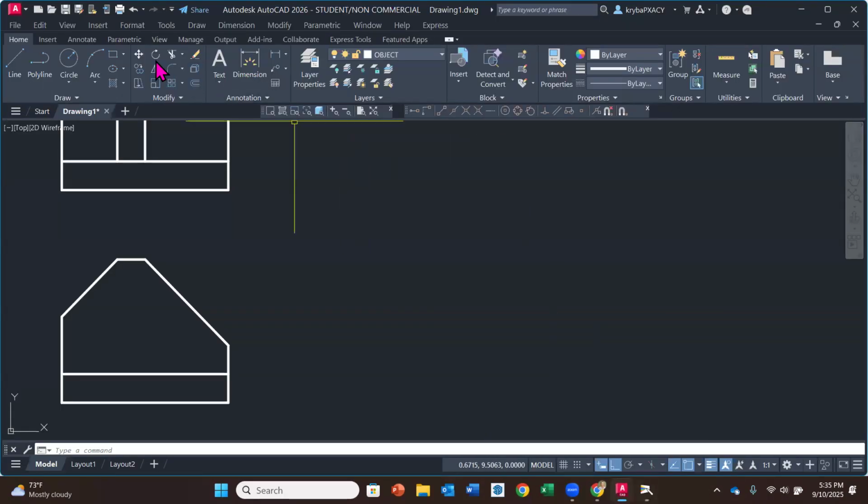So let's make sure that your snapping references are activated. I'm going to do my line command, and here I'm going to just activate the bottom and I'm going to go straight over. Now, you don't have to worry about spacing being exactly the same value as it is between the top and the front view as the right side to the front view, because we aren't using a miter line to create this. If we were using a miter line, then that distance would have to be the same, okay? But we're not. So we're simply going to left click, and I'm going to go straight over.